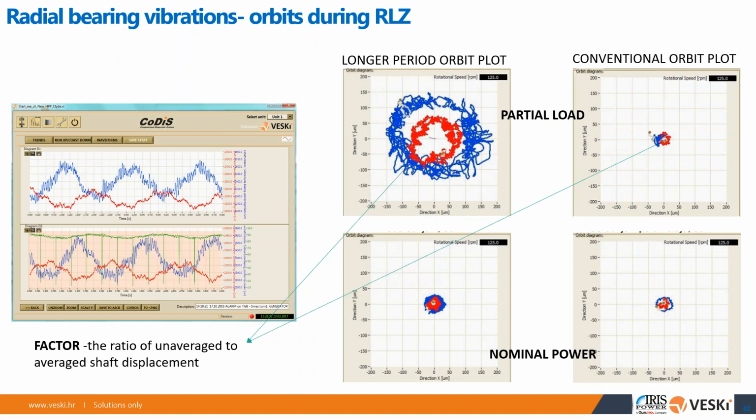And the third one we usually put on top of the rotor, again on the concrete foundations, to see the complete rotor lift. So we get the turbine cover lift, which also sometimes grows a little bit when you put pressure in the turbine. Then another one is we want to measure how much the rotor lifts to the bearing. And the third one is we want to measure how the whole structure, meaning rotor and everything, vibrates. And we also need the accelerometer in the axial direction to confirm that as well.